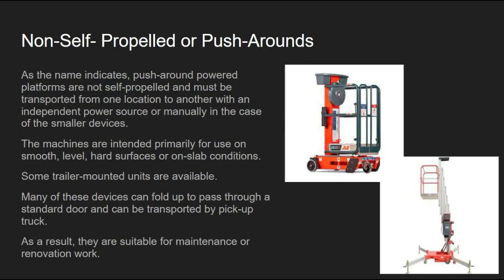The non-self-propelled, or push-around. As the name indicates, push-around powered platforms are not self-propelled, and they must be transported from one location to the other with an independent power source, or manually in the case of a small device. The machines are intended primarily for use on smooth, level, hard surfaces or on slab conditions. Some trailer-mounted units are available. Many of these devices can fold up to pass through a standard door and can be transported by a pickup truck. As a result, they are suitable for maintenance or renovation work.